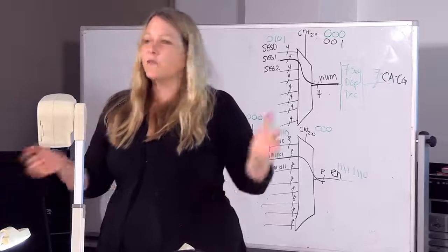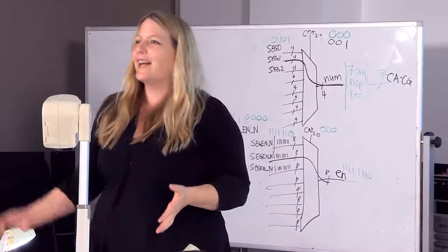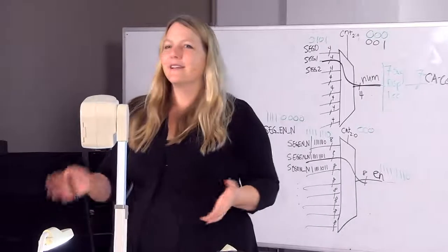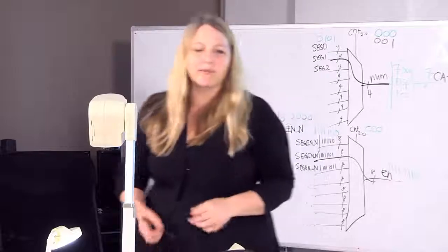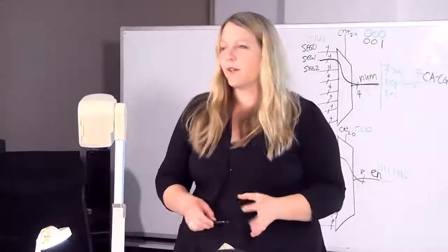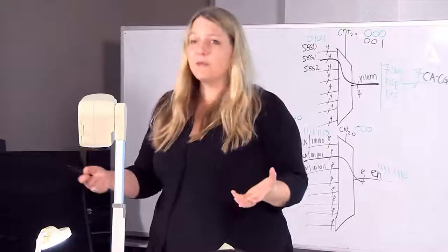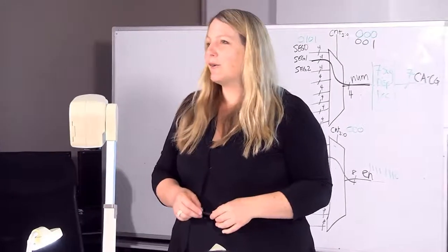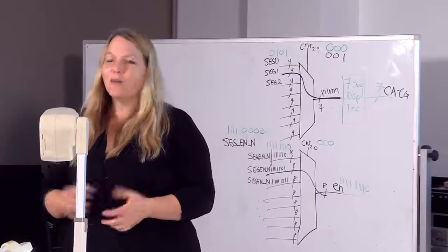If you haven't done it before, you can follow what's in Module 1. It describes the details of adding the Verilog code, adding the constraints file to your project, compiling it, synthesizing it, and then downloading it onto the board, which we've done the last part. But if you want to go through that first step, once you start modifying the code, now you have to compile and synthesize, which can take some time, 10 to 20 minutes. So not something you're going to be doing, oh, I made a small change, right?